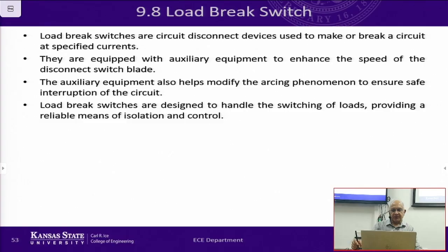Now, this is not suitable for fault interruption, so you can only open this under load conditions. If you are trying to isolate a particular segment of the feeder, these switches can be installed and opened to break the circuit under normal operation.